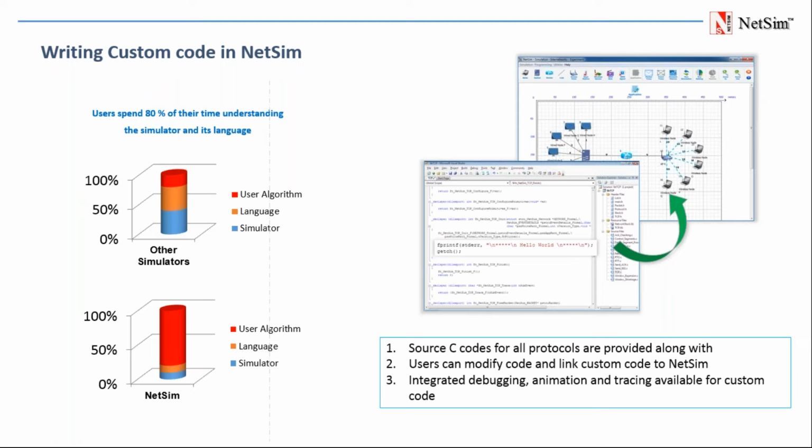So considering these difficulties, Netsim has been designed with its GUI feature along with custom code editing, where we can design and analyze our network in GUI, and if we wish to change existing protocol or create our new protocol, that can be done using Microsoft Visual Studio 2010, where we can save our files in a DLL extension, and link it with Netsim GUI.